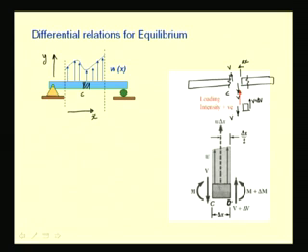So, this picture shows the free body diagram of such an incremental beam section. So, at C we have this shear force and bending moment all in the positive sense, and for a section D which is at a distance of delta x, we have the shear force and bending moment incremented by a small value delta V and delta M, and we have a loading curve, and the total load in this section is W delta x.